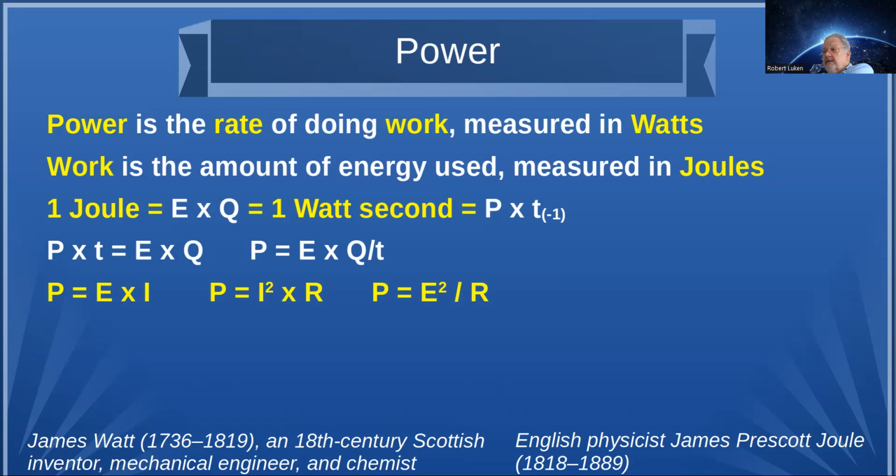In the real world, that's not the case. There's very few antennas that are actually going to be 50 ohms. If you look at your standard dipole, which most antennas are a derivation of, it's two quarter wavelength long pieces of wire with the feed line connected in the middle.